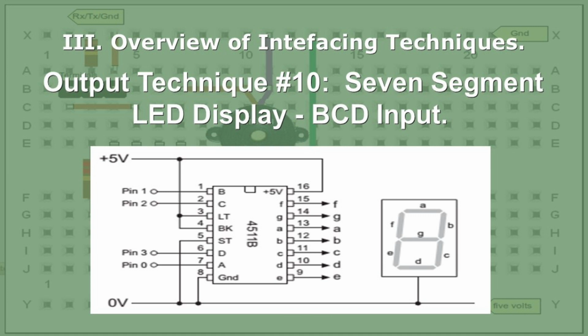7-segment LED. Notice here that this is a BCD input. So you're going to have 4 binary digits, with which 1001 would be 9. That's a BCD input, for example. And you can see the 4 pins right over there. And 0000 would turn on segments, let's see, F, E, B, C, D, and A, for example. Numeral 1 would be B and C segments only.